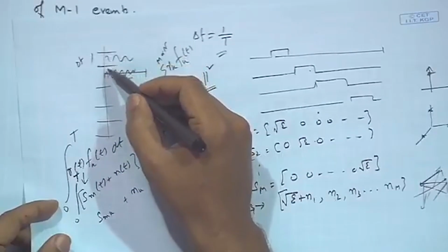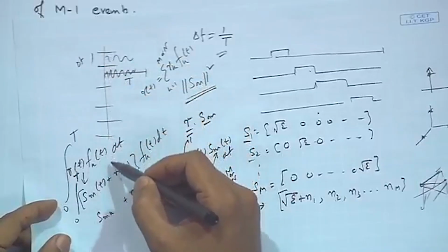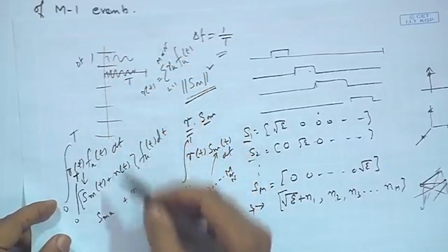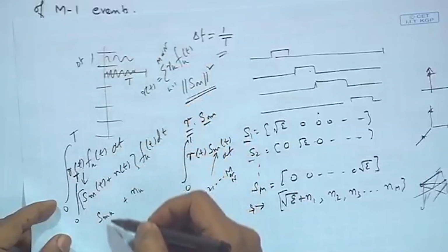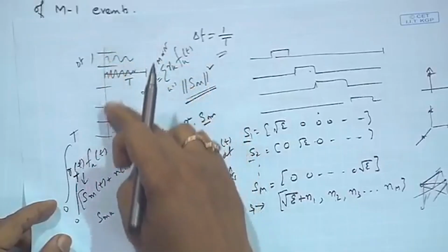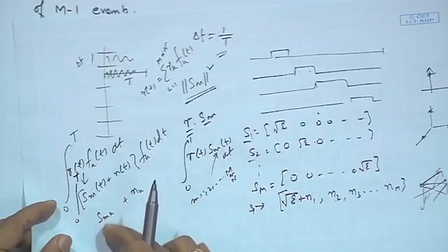As we increase k, we keep on increasing the number of frequency bands. So, as we keep on increasing the number of frequency bands, we are tending towards using a very, very large bandwidth. As k tends to infinity, you are tending towards infinite bandwidth. So, what we have in this case is the probability of error is traded off with the bandwidth.